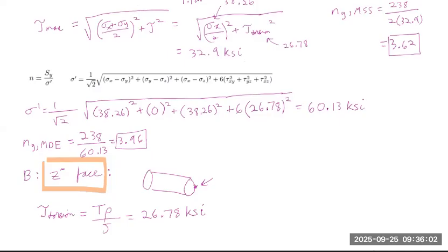We now have the transverse maximum shear stress for a circular cross section. The maximum shear stress is given by 4V over 3A, where A is a circular cross section at point B, using the smaller diameter because the smaller diameter is more critical.